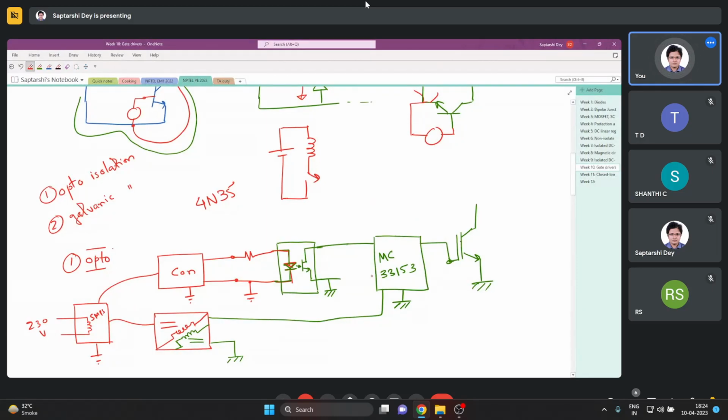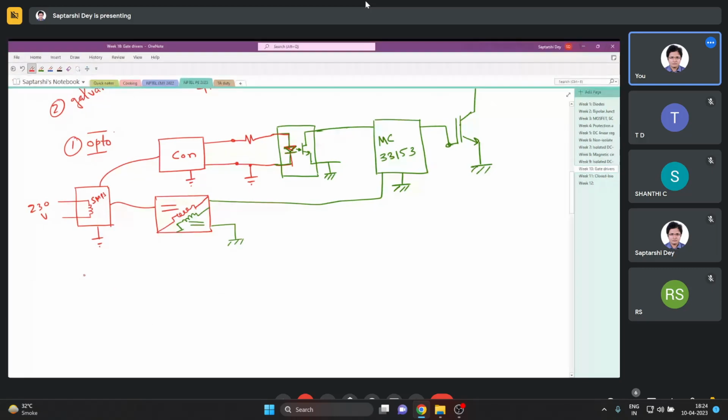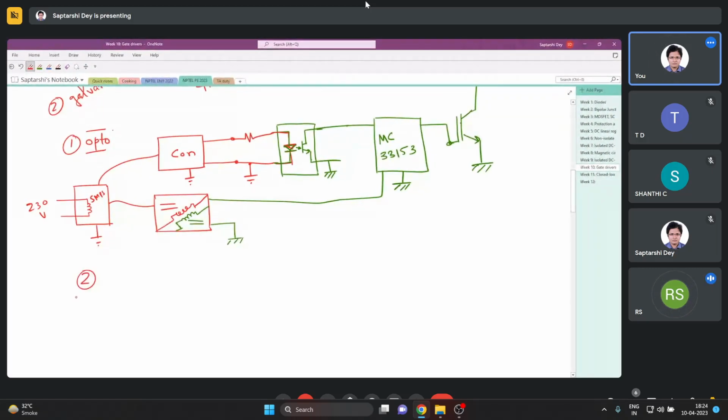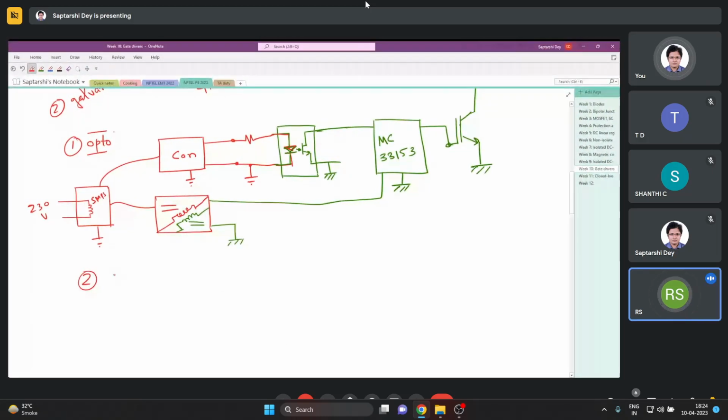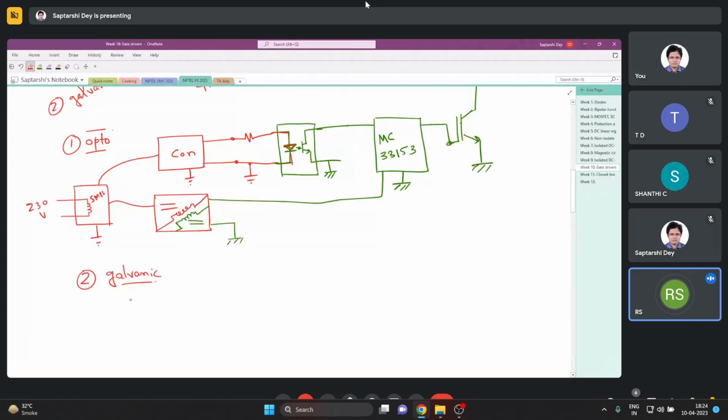Such kinds of converters and gate drivers are very much used for voltage-driven devices, MOSFETs, IGBTs. Basically, wherever we need a difference in references, suppose some part of the circuit will have a potential at every node with respect to some reference, and the other part of the circuit will have node voltages with respect to some other reference.